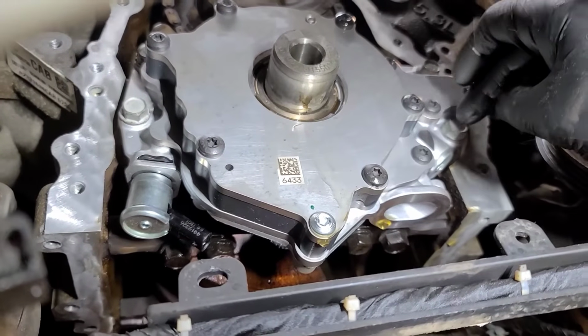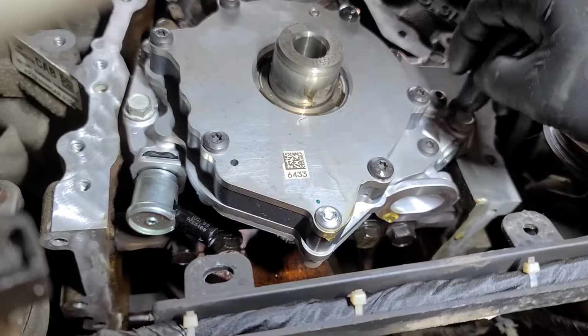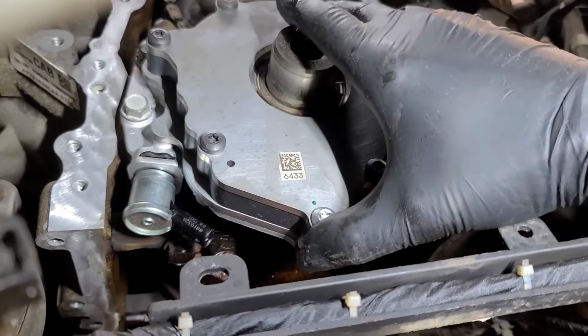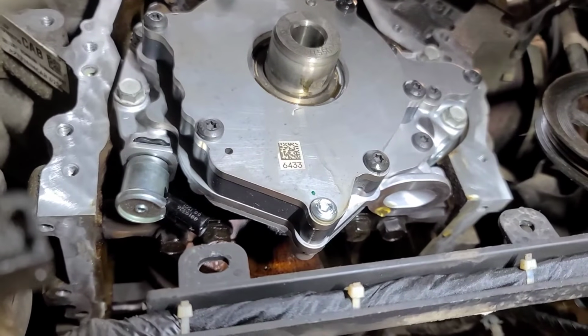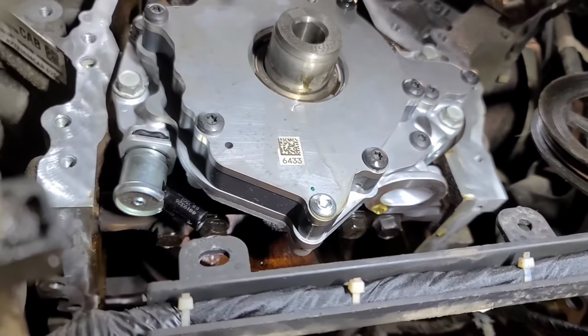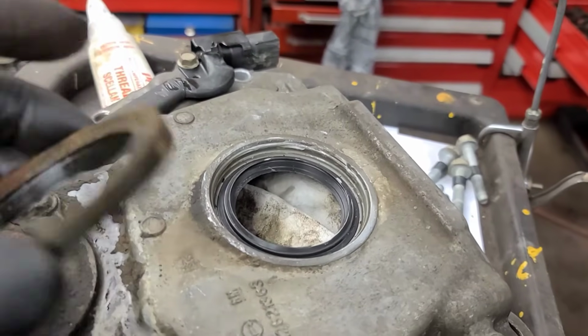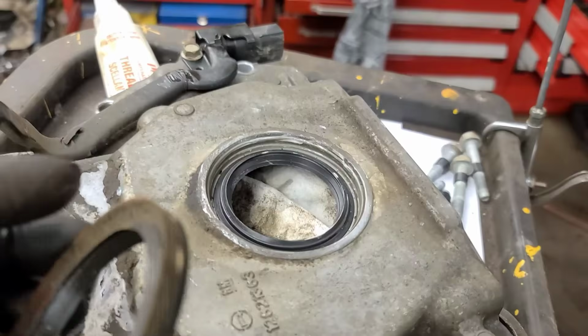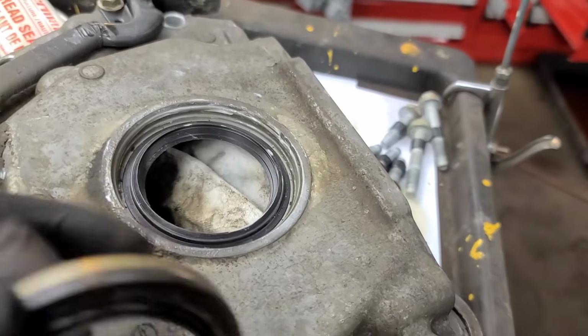There's little nylon spacers in each one of these bolt holes, but there is a little bit of play on them still just the same, but the service literature says push upwards on the pump. And again, 18 foot-pounds. So it's highly recommended to replace the timing cover seal because you have it off. So I've got a new seal in there. I used thread sealant around the outside of the seal. I still have to put some grease on it.